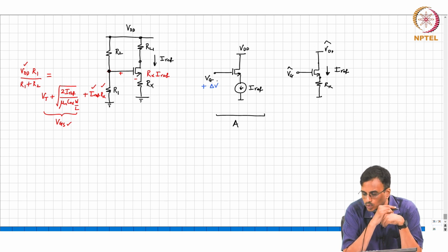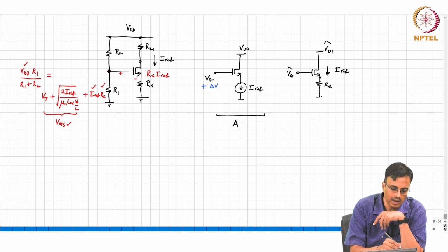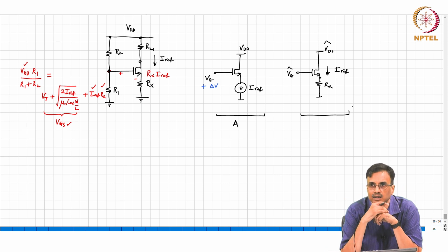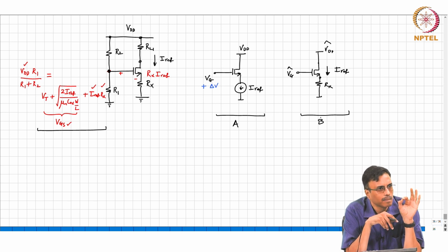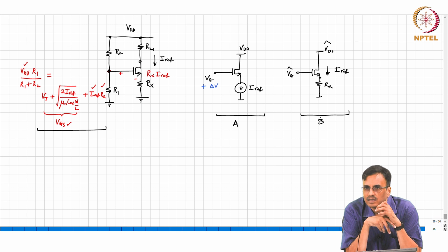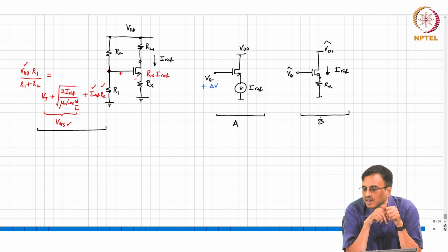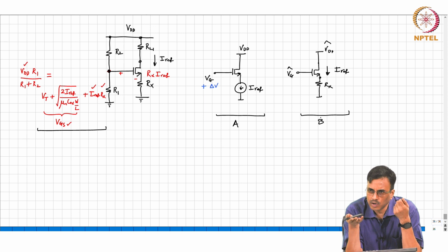Based on this discussion, how will we figure out if a certain Rx qualifies as a large Rx? We changed Vg by a little bit and observed the change in ID. When we say the current doesn't change, it doesn't make sense to talk about the absolute change in current. It only makes sense to talk about a relative change in current, correct?